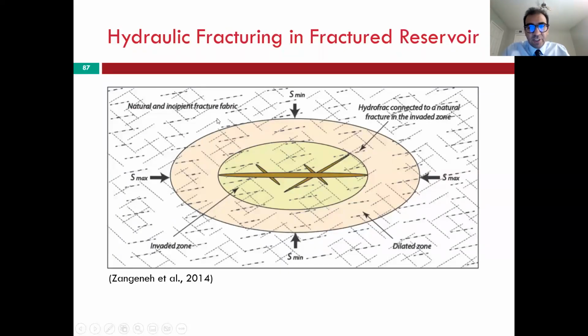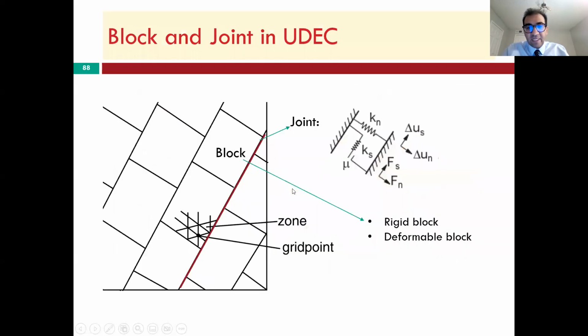For instance, one of the applications is that we can simulate this system in UDEC or 3DEC. We have an area of fracture in the model. We have in situ stresses that we simulate and apply in the model. Then, with that state of in situ stresses, we apply hydraulic pressure inside the fracture. Then we can study the amount of fluid infiltration into the fractures, as well as the strain condition, the movement and displacement of the fracture.